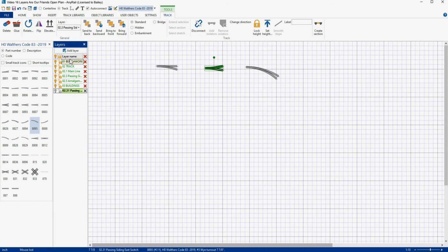Hit enter. Now come up here and I will arrange the names. And you'll notice it now goes 02, 02.1, 02.3, 02.31. And I can keep going. I can keep adding in a sublayer to this layer, to the 02.3. Makes sense? Meaning that if I wanted to add a sublayer here that's only tied to the amalgamated fish processing, I would make a new layer that would be 02.51 or 02.53 or whatever I want, and come up here and arrange it and they'll drop in order down here.